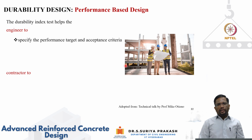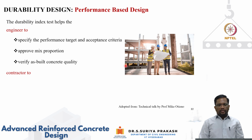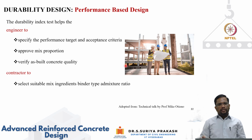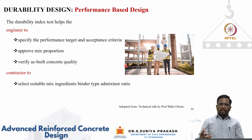So you are quantifying the durability performance, and it can also help the engineer to approve the mix proportions, and it can also help the engineer to verify the as-built concrete quality. From the contractor's point of view, it now gives leverage to select suitable mix ingredients rather than just specifying, as in the prescriptive approach, where we know that only the minimum cement content or maximum water-cement ratio, or for certain mechanisms, some conditions are given.